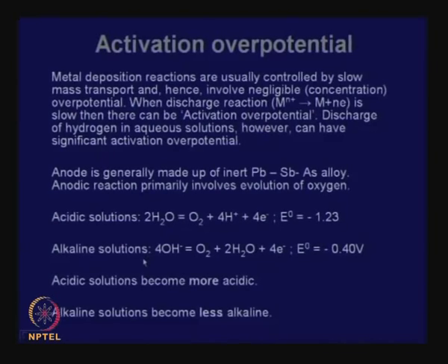In alkaline solutions, the alkali dissociates and gives oxygen and water. Acidic solutions therefore become more acidic, and alkaline solutions become less alkaline. So, in acid leaching processes, that is an advantage. Acid leaching processes followed by electrolysis in theory consume no acid, because you have consumed acid and produced an electrolyte, you electrolyze, you generate acid, and it goes back.